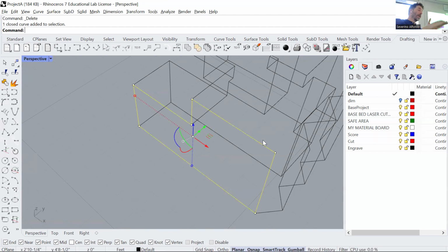If that's the case, if it's a very thick material, you're going to have to do an offset of the curve in one of the directions, because otherwise you're adding to the exact dimension of the model. Does that make sense? So you're going to have to plan ahead and do that kind of a shift and offset of the different line work because of the thickness.